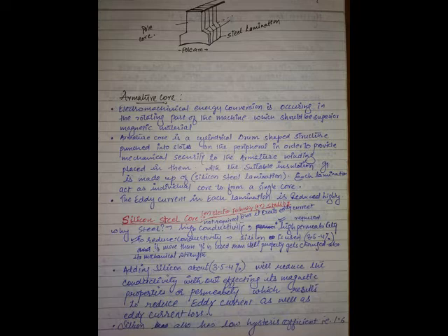Due to high peripheral speed, if the spark spreads on 3, 4, 5 commutator segments, the coils inside get short circuited and it will provide a huge current. Huge current flows in the coils inside, and they will burn. Therefore, commutation plays a vital role.